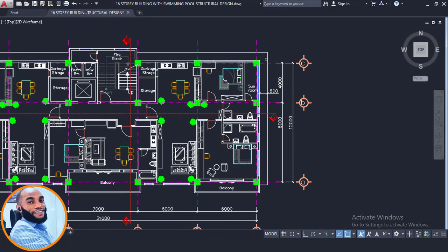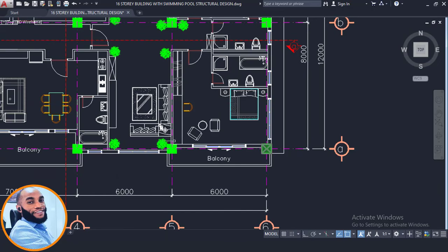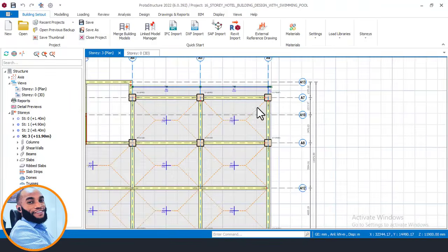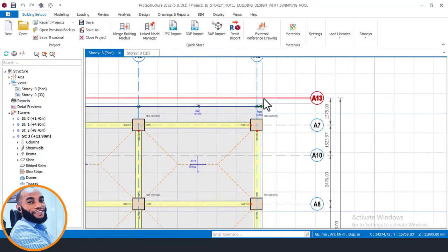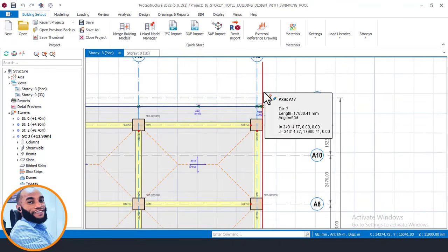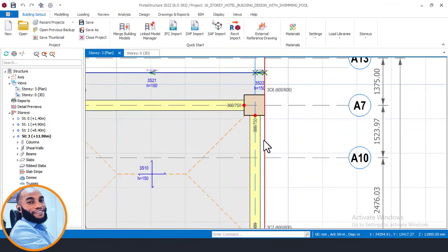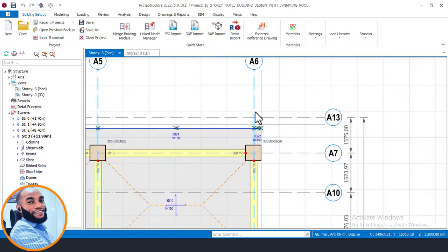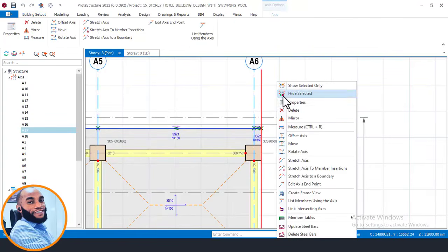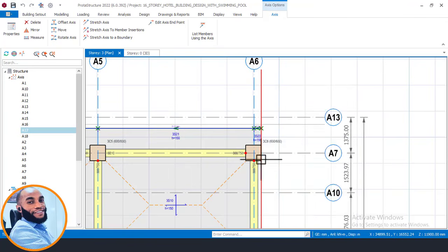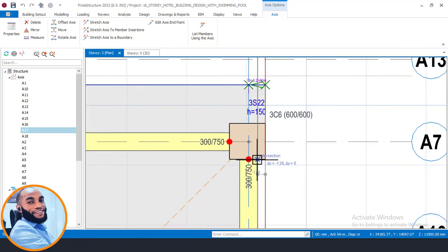It flows all the way down from this place to this place here, and then we have our balcony slabs around here. Okay, so right now I'll open the software again, and the first thing I'll do is to offset this our grid line. I'll click on this place, click here, and then copy this grid line. I can choose to copy or offset. Then keep this here first.